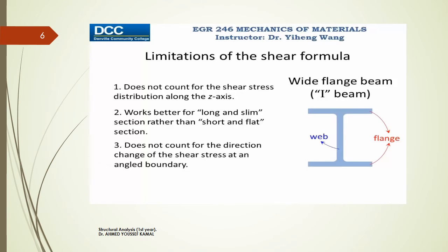And thirdly, the shear formula does not account for the direction change of the shear stress at an angled boundary. For example, according to the shear formula, the shear stress distribution looks like this, when in fact, the shear stress should be along the boundary.